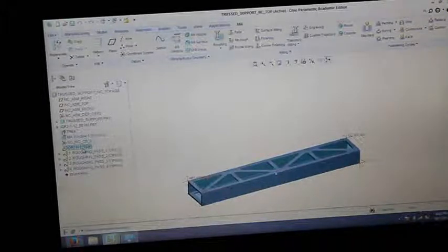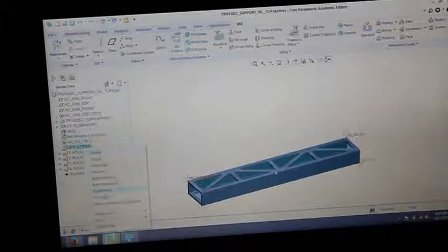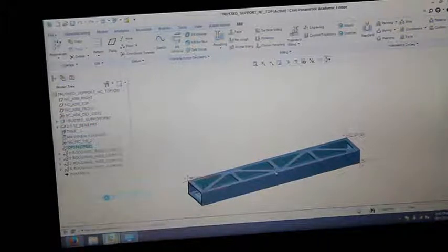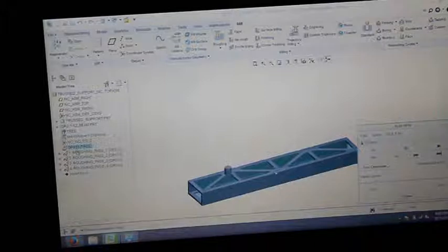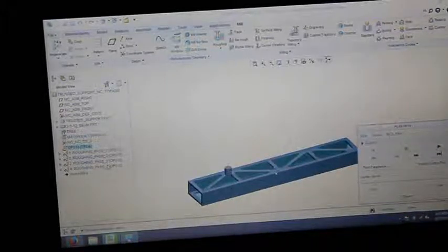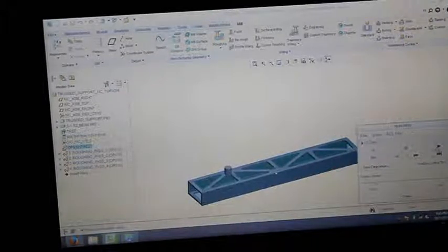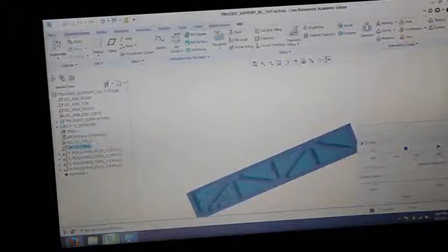Now all these operations are as they should be, and if you want to check your part before running it on the CNC machine, a great way to do this is actually go to CREO. You right click on your operation, which contains all your actual cuts, and you hit right click, play path, and if you just hit this little button, we want to slow this down maybe a tiny bit. We'll check what we want later. So as you can see, it's doing a scan type operation.